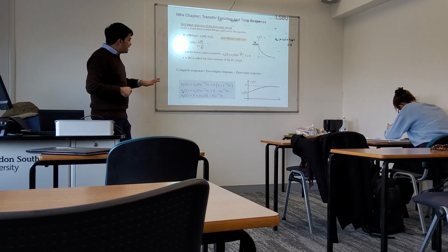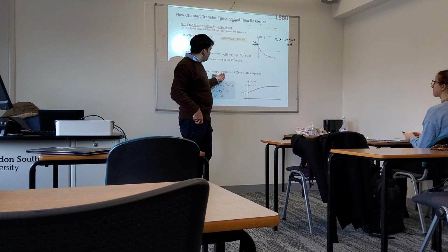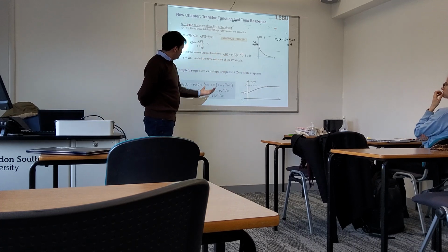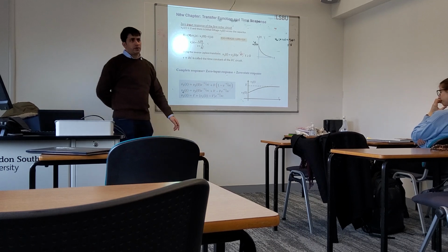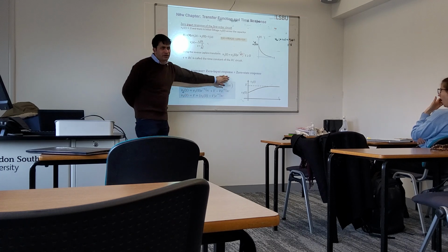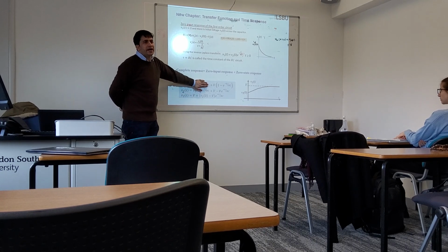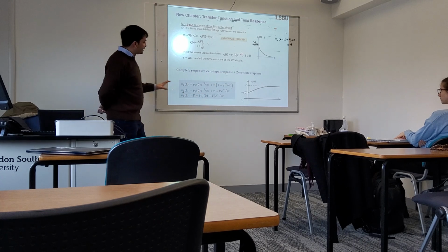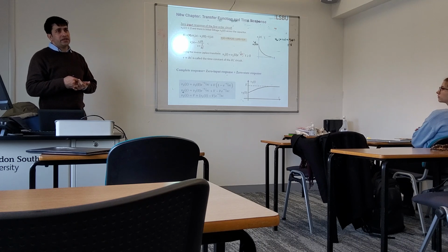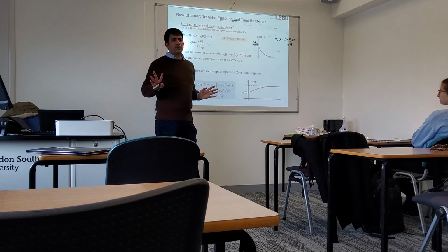Okay, now we said that the complete response for the system is equal to the zero input response plus the zero state response. The zero input response we just calculated, which is this one, and the zero state response is this one. So if there was no initial state, and consider that there was no initial charge in the system, this term will go to 0, and only this term will hold. So this is the complete response for a system where we consider the input as well as the zero state. One important thing is this zero input response will stay the same, right?